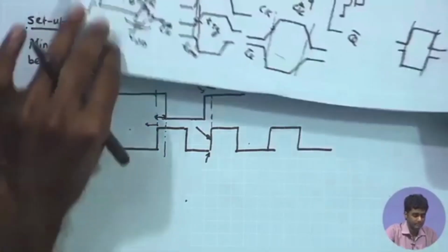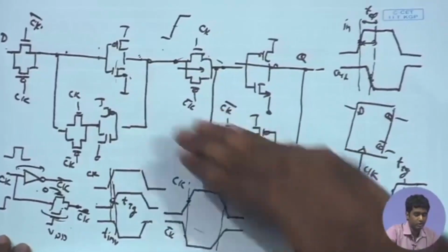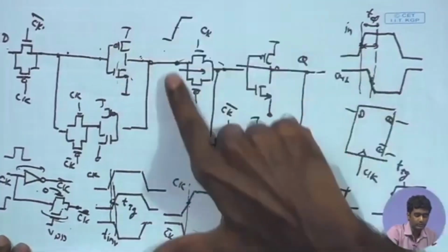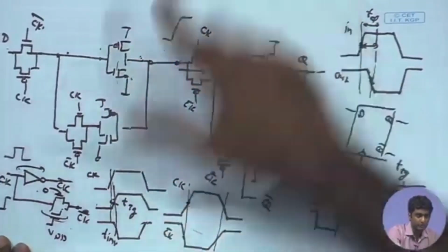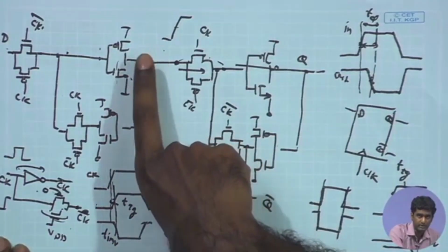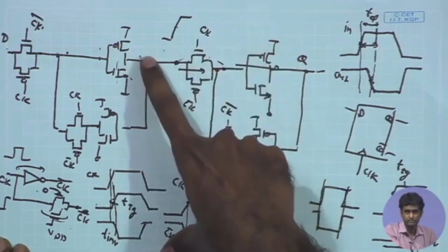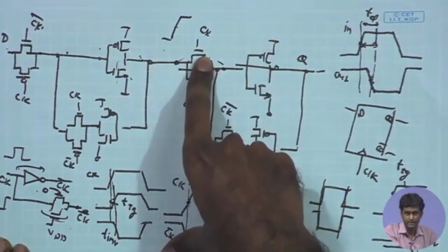So, that depends. If I look at this circuitry, what is happening when the clock is going from low to high, when the positive edge is coming? Before the positive edge, the data over here is supposed to be stationary, and when the positive edge comes, the data over here is supposed to propagate to the final output or be sampled by this particular transmission gate.